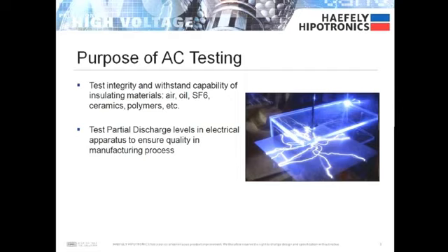You need to test to make sure that it will withstand those voltages. Another test or measurement that's done very frequently to test the quality of the insulation is a partial discharge test, which we won't get into in too much detail on this WebEx, but on other WebExes this information will be available.